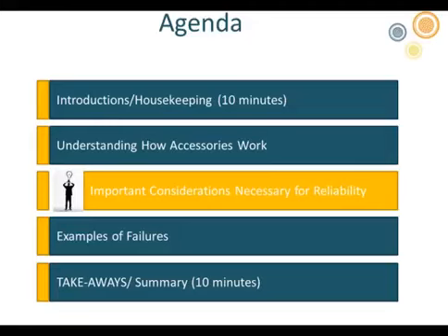because of the smaller distance you can have, especially with switchgear getting smaller and smaller. It allows you to have a shorter termination in that switchgear and still have lower surface stress on the termination, which will improve the reliability.